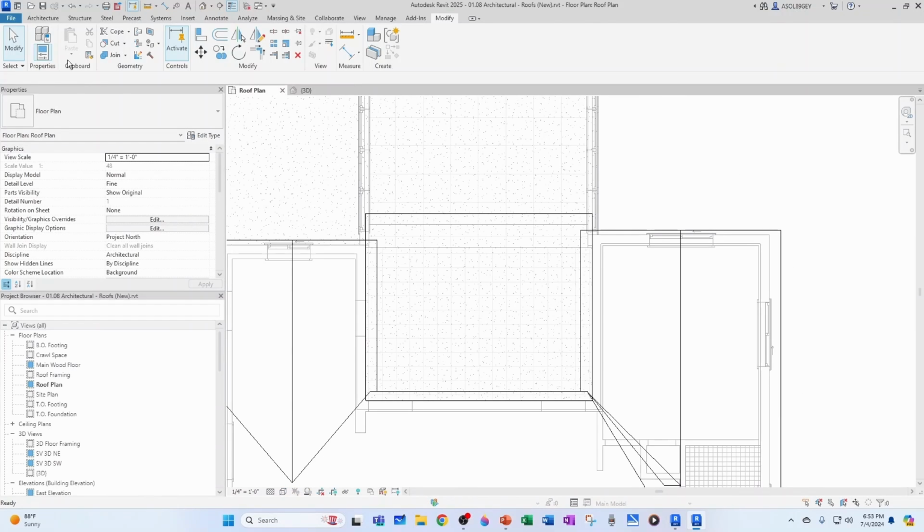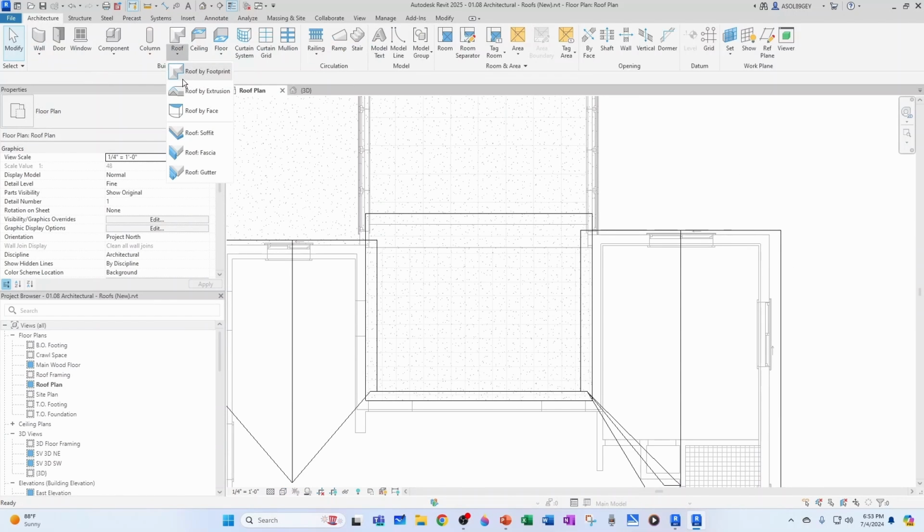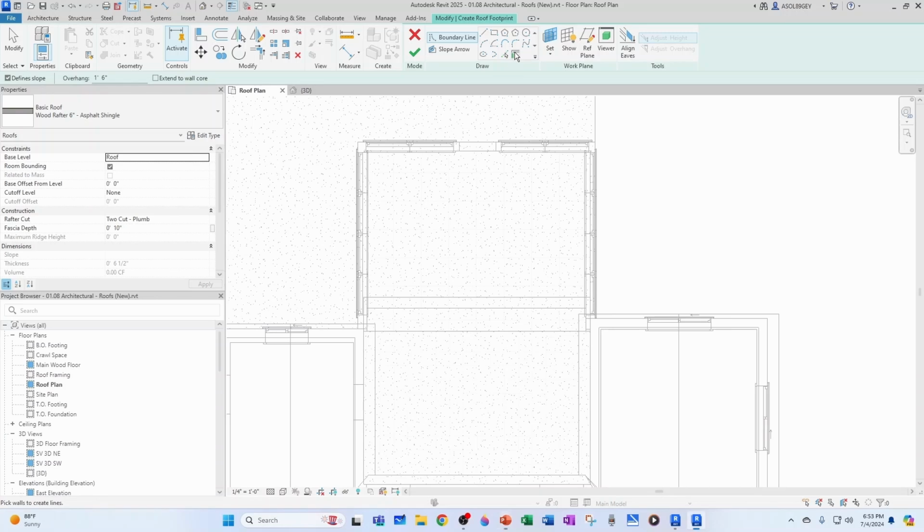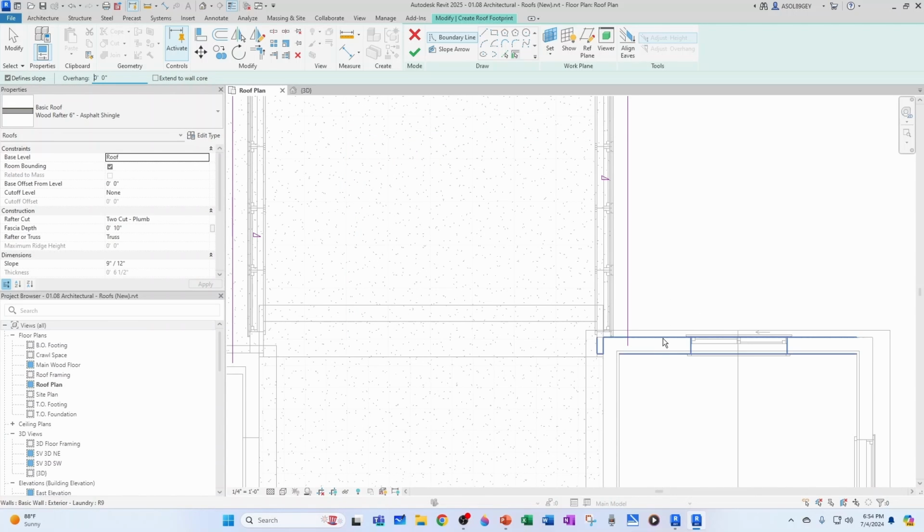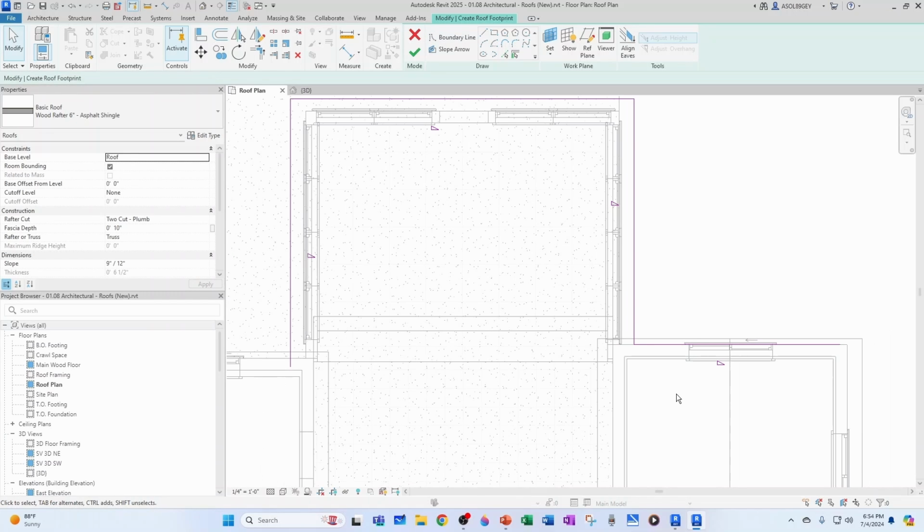So let's go to Revit, and again we go to architecture, roof by footprint. We're going to pick some walls, and we said we were going to have 10 inches of overhang to the west and to the east. To the north, we're going to have 8 inches, and to the south we have no overhang, and we're using this wall as a reference. That's very good. I'm going to do TR from here to here and from here to here.